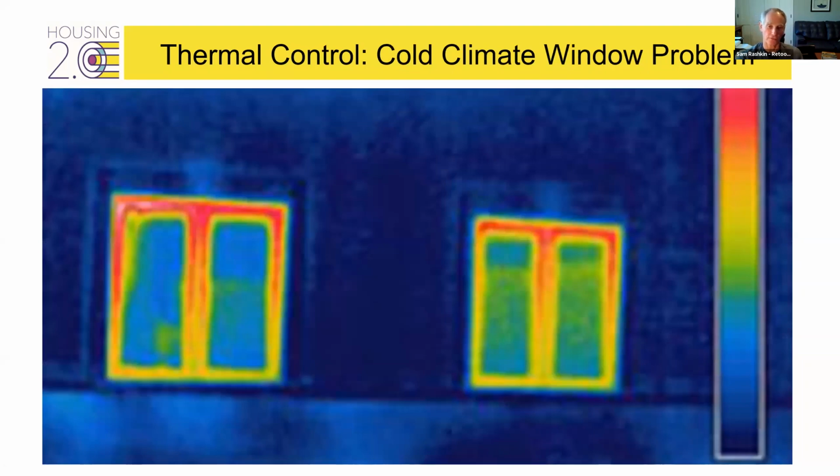And then recognize the next funnel for thermal flow in and out of the home is our windows. And this is particularly going to be in colder climates. In warm climates where your cooling is the major load, the cooling design temperature will be about 95 degrees. The indoor temperature may be 70. So you're only looking at a 25-degree delta T. But in cold climates, it could be 0 degrees outside, 70 degrees inside. Now you're looking at a 70-degree delta T. So this is a cold climate issue with conventional, even Energy Star windows.